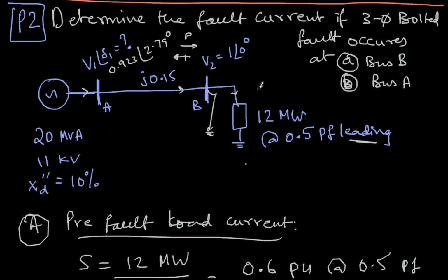If there is a machine here like a synchronous motor or synchronous generator, it will have an internal voltage. That internal voltage can feed a reverse current into the fault, but in this example that is not the case, so therefore we are not calculating that fault current here. This is assumed to be some kind of a voltage dependent load with a fixed impedance value. So when this fault goes zero, this current will not be considered.